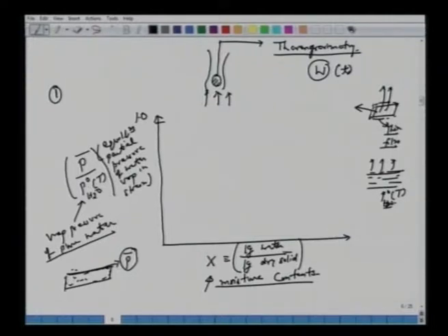That means we are starting with a very large amount of this X content. You will expect that you are following this line of 1: the equilibrium partial pressure of water vapor at the surface is the same as the vapor pressure of pure water. So you will expect that as the moisture content decreases, it stays at 1.